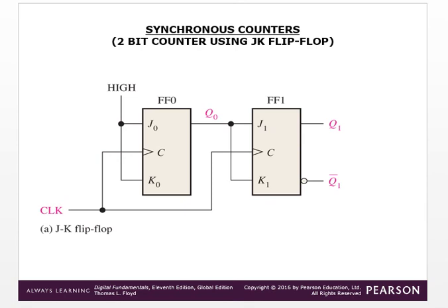That is why an asynchronous counter is called a ripple counter. You know, ripple in water. A ripple means it is going one by one. Okay. So it is slow also, it is serial. But the synchronous counter is very fast, because see here the clock is connected in parallel. Okay, the same clock goes to each flip-flop. So it is very fast. But as I told you, one of the disadvantages of this I will tell later.